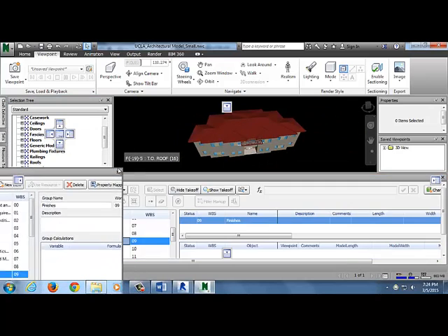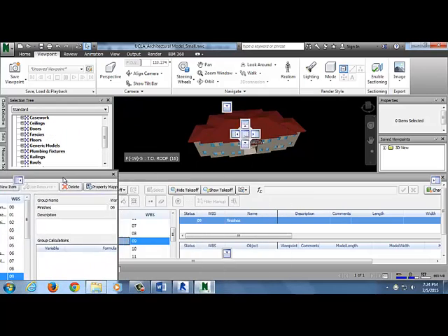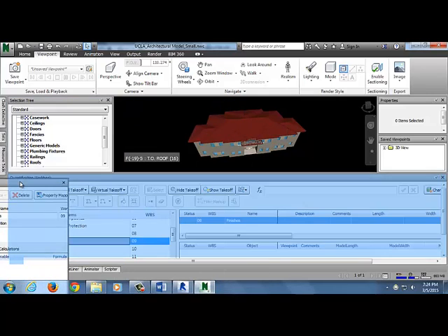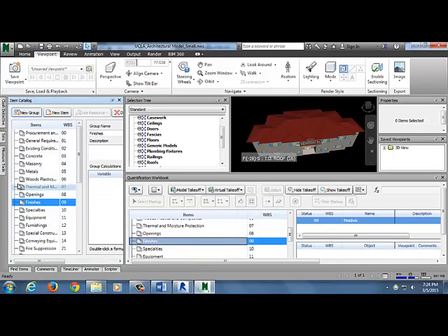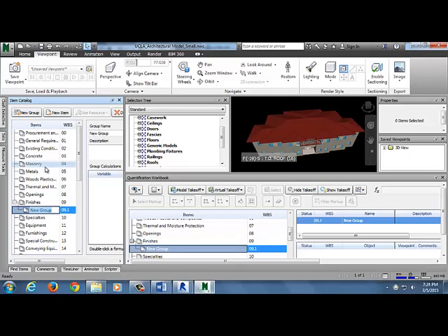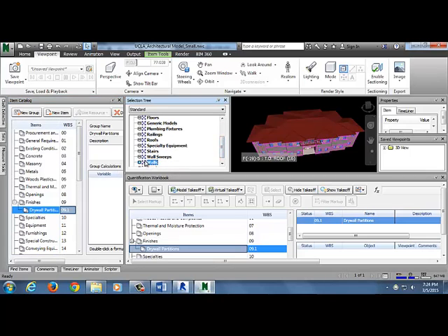So my question: the walls you're going to put in Division 9, somebody would like brick walls in Division 4. Yeah, CMU and masonry. So under finishes, Division 9, I'm going to put a group called drywall partition. Yeah, drywall. And then I'm going to come into my walls.